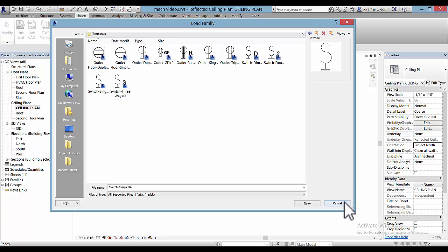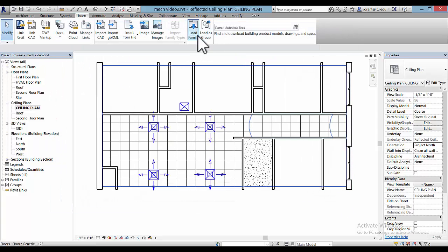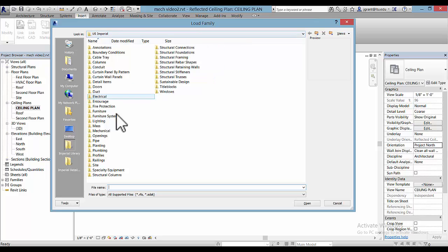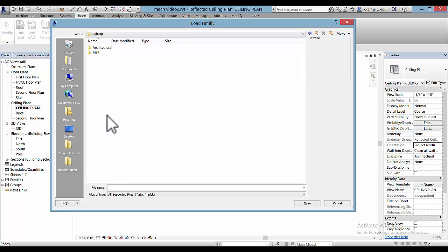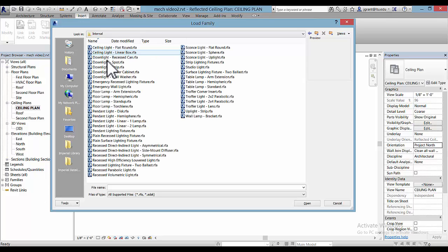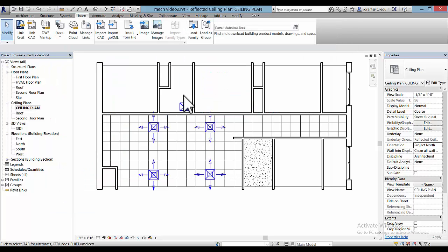For an electrical plan that has information stored, we need to go underneath the MEP lighting to go to internal and find the light fixtures. The light fixtures that we're going to use are the troffer lights, and we'll stick with the 2x2 in the panels, the ceiling panels that we're using. Now we can go to the System tab and you'll see all the different settings for electrical.